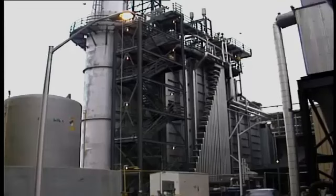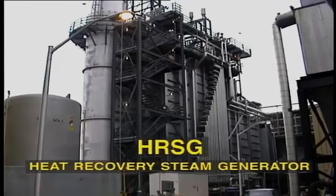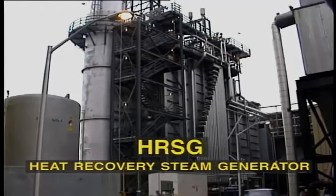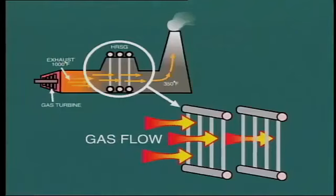The usual term for this type of boiler is HRSG, that is, heat recovery steam generator. In this type of boiler, the temperature of the gas entering is usually about 1,000 degrees Fahrenheit, and the exit gas temperature to the stack is about 350 degrees Fahrenheit. The heat is extracted from the gas by placing banks of tubes directly in the path of the gas flow. The tubes are often finned to increase surface area and heat pickup.